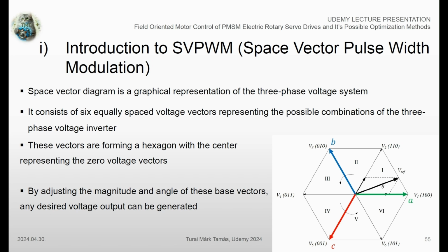The resulting output voltage vector is being time modulated with the help of a high frequency carrier signal, which means that, for example, if we would like to output a vector, let's say 30 electrical degrees counterclockwise measured to the A-axis, then we shall output the V1 and V2 base vectors for the same amount of time in order to receive an average value of a 30-degree voltage vector.